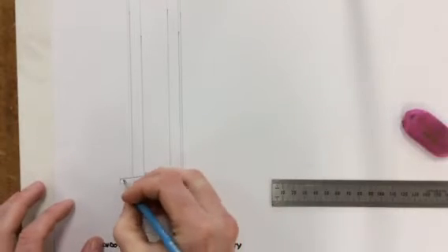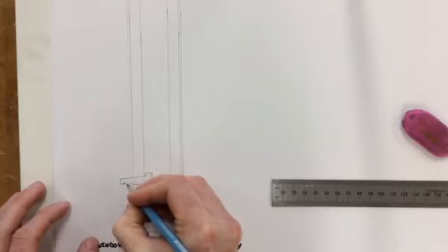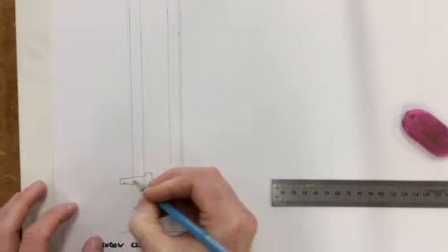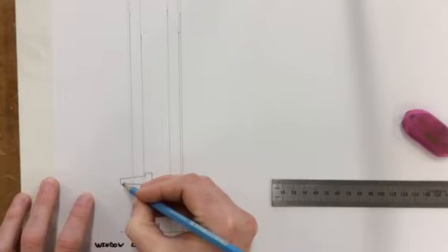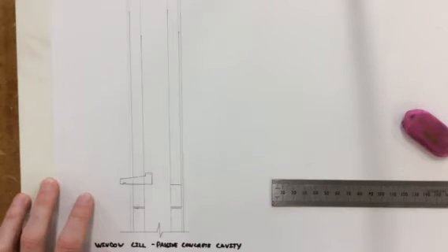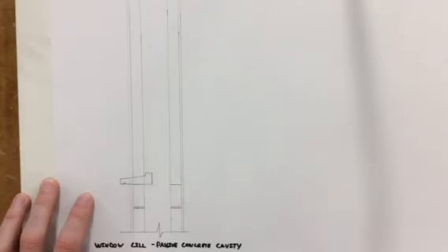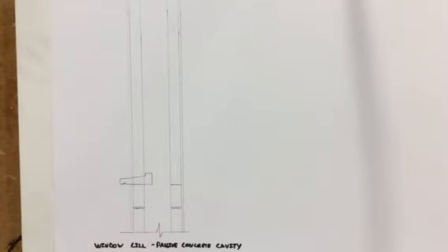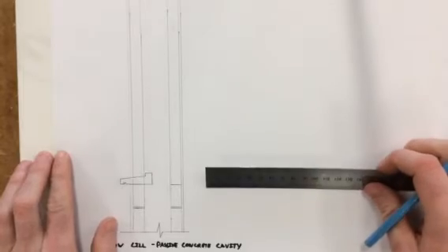Then another design will be here at the front. Here at the front you would have what's called a drip. It's a small indentation that's put into the windowsill, that as the rain comes down, flows around, comes into the drip, and the drip is designed to make it fall down, to disappear, or to go down the outside of the wall. So then we want to carry on with the likes of this.